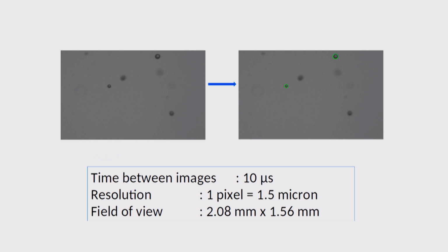Imagine that just now we said that if you want to measure the velocity, this particle has to follow the flow, right? That means it should be small enough. If it is heavy, then what happens? It will just settle down with gravity, so it will not follow the flow. You will have a net component, it will go. So you have to make it so small that it will just follow. Except for the drag force, there should not be any net force on it.